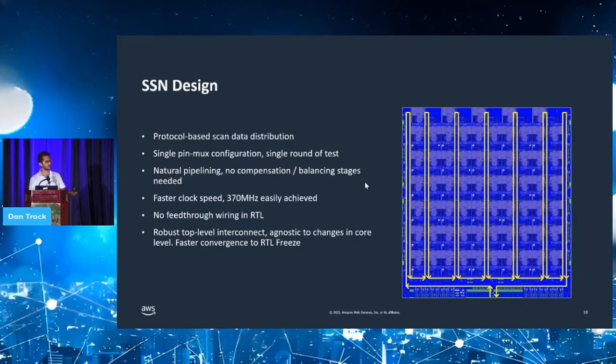And the clock speeds are much, much higher because of those short hops. So here, almost for free, we achieved almost 400 megahertz very easily. Whereas with the legacy scan design, we had to work hard only to reach the 200 megahertz.